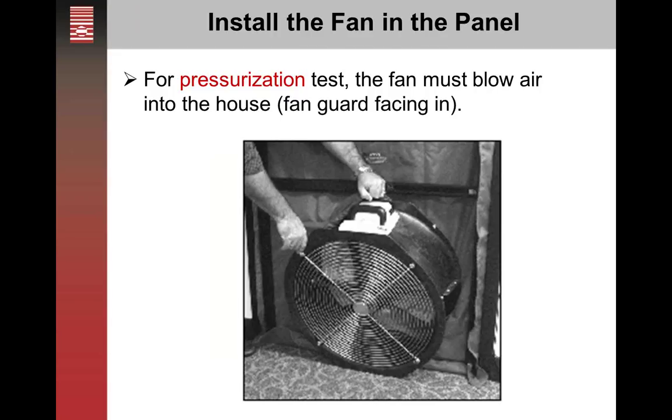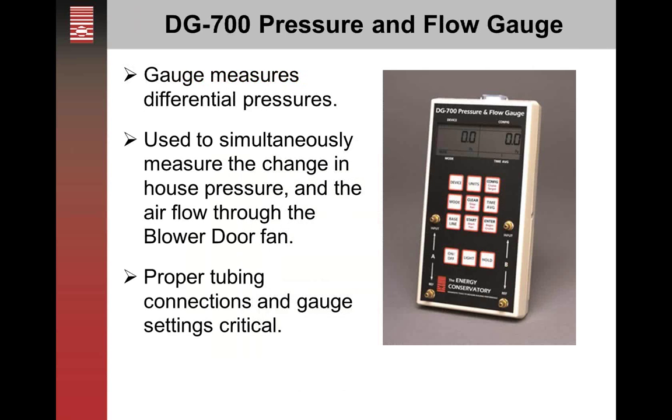When you're pressurizing, you will actually open those all up. So your number might be a little bit smaller when you're depressurizing and a little bit larger when you're pressurizing. If you really wanted to try and be very accurate, you could do both tests and take the average of those. But your numbers are going to be very close.